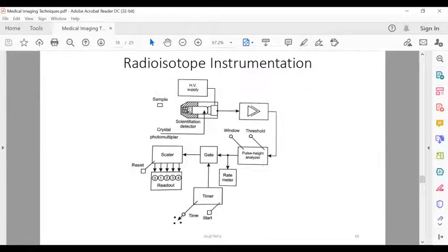And here the nuclear radiation detectors used for medical applications utilize the light flashes caused by the radiation in a suitable medium. So here you can see from this diagram, the scintillation detectors, which are used for gamma rays. It has a crystal through which the radiation, when passed, gives an output pulse at the photomultiplier tube. Now the amplitude of the pulse is proportional to the energy of the radiation, and this helps to reduce the background by means of a pulse height analyzer.